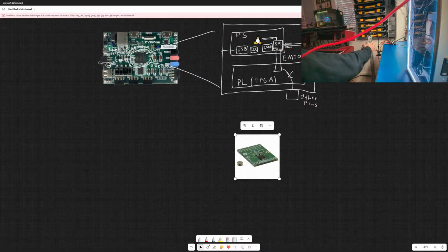This is interesting because typically quadrupeds or any sort of robot dogs will not have direct drive. In other words, generally they'll have a gearbox or gear transmission to step up the torque. But because these are such beefy motors and they have a decent amount of torque already, you don't really need a gearbox, although there's some debate as to whether the weight of these motors is worth the fact that you can have direct drive.